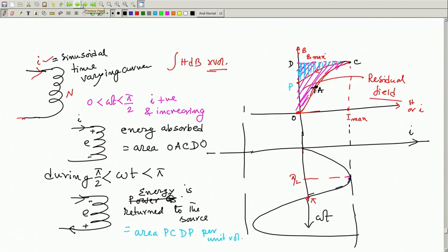In our case, current will be alternating in nature. I am not saying whether it will be sinusoidal or not, but it is alternating. Current will increase, will reach a peak, then it will decrease and so on. When you first switch on, suppose there was no residual magnetism present in the core, then this is the BH curve, this point will go up, and when it reaches I max, this axis incidentally also represents current in some other scale.